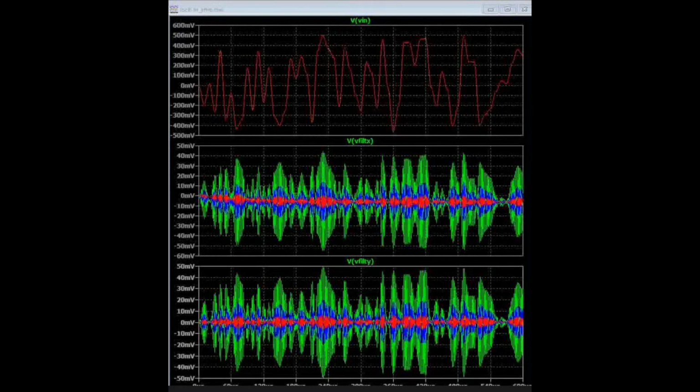So in order to extract the real information in this signal, the real repetitive signal that is hidden in this signal, you would need an amazing instrument called a lock-in amplifier, which has the ability to extract both the phase information and the amplitude information with respect to the known frequency, that is the frequency content of the signal. So if you assume it's 30 kilohertz, then it will tell you what the amplitude of the signal is and the phase of the signal with respect to a reference signal that is also at 30 kilohertz.